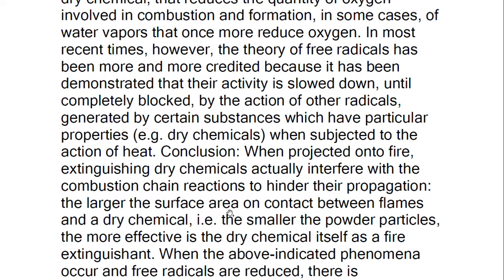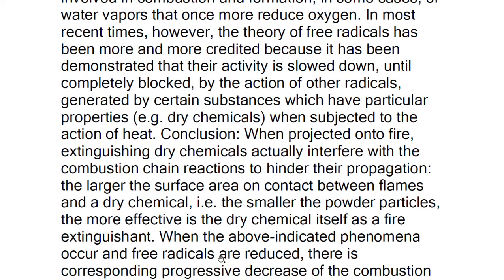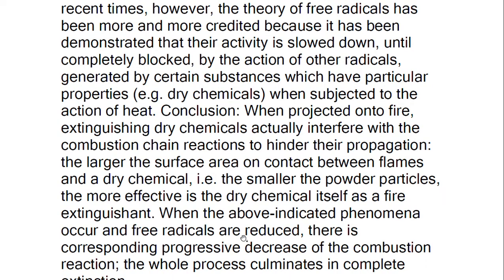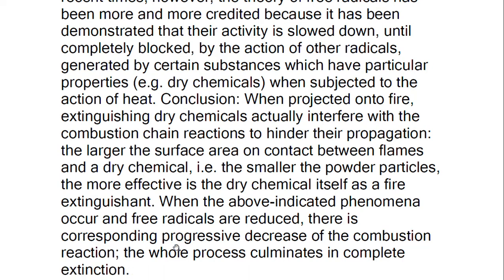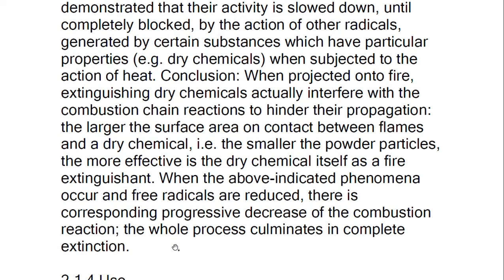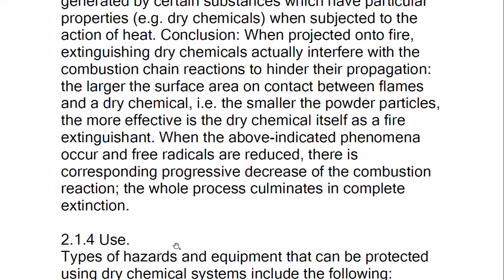The surface area of contact between flames and the dry chemical matters, that is, the smaller the powder particle, the more effective the dry chemical itself is as a fire extinguishant. When the above indicated phenomena occur and free radicals are reduced, there is a corresponding progressive decrease of the combustion reaction. The whole process culminates in complete extinction.